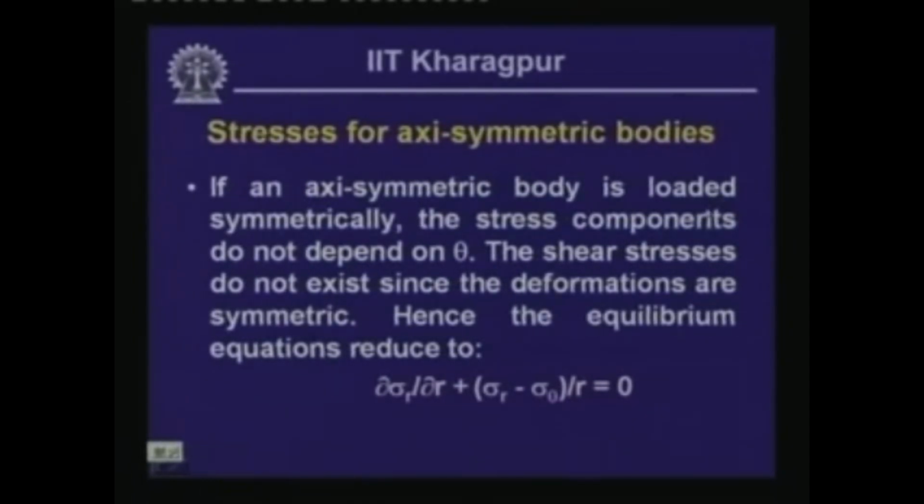Now, as I said, we encounter several kinds of structural elements where the boundaries may not be perfectly straight. You can have a curved boundary over which there could be stresses, like the radial stress, described by the stresses σr and σθ.